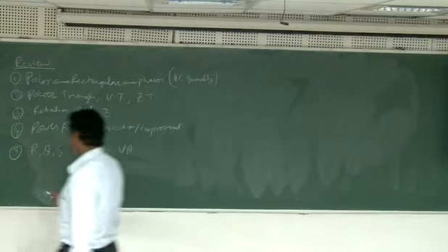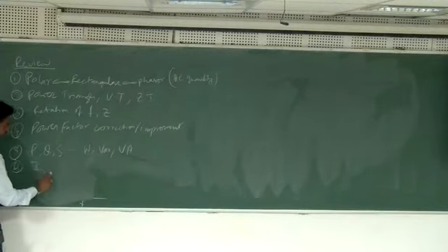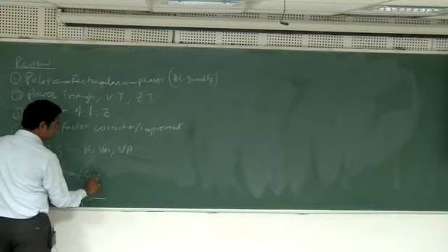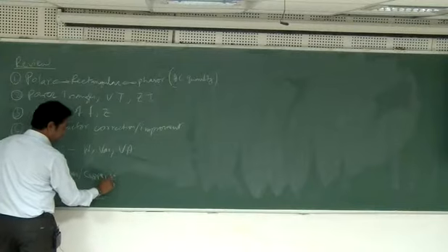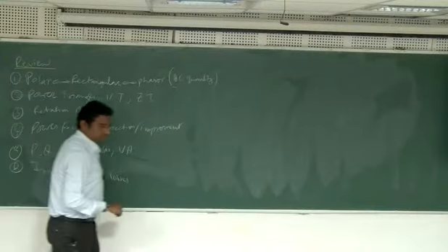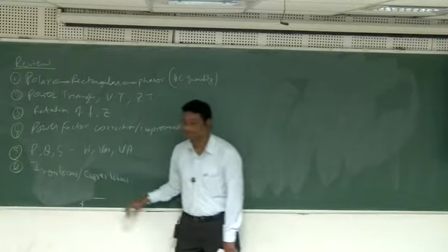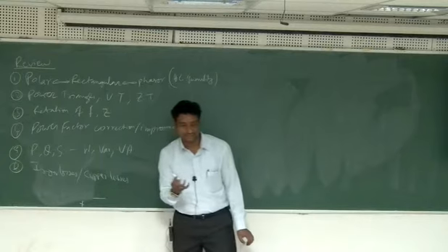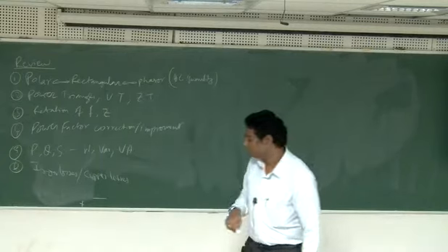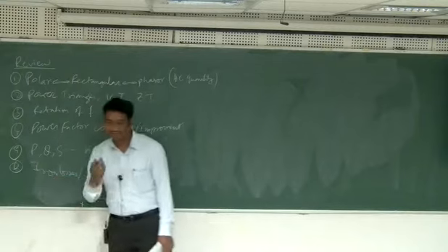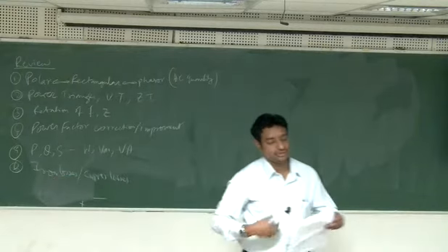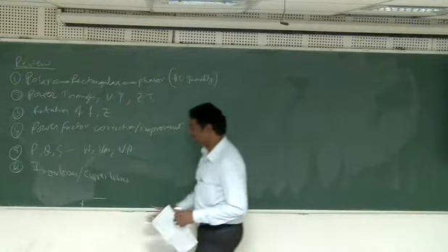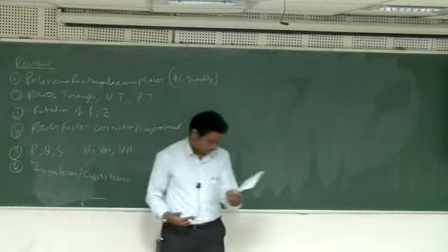Yeah, there was one problem about iron losses and copper losses in a coil. Whether it is iron loss or copper loss, you can model it. Copper loss is right away because of the resistance of the copper wire, whereas the iron loss is because of the heating of the core, which you can also model in the form of an effective resistance in the circuit, and you can solve that. That's what we have seen from one of the problems.